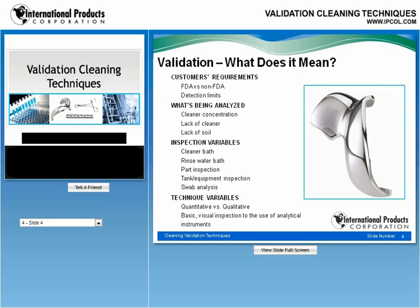We feel that these companies can be classified into two broad categories: those who are regulated by the FDA and those who are not. In general, it means that the detection limits for both of these groups are vastly different. Typically, FDA-regulated companies have very low detection limits. They need to know what the parts per million or even parts per billion concentration of cleaners are, versus non-FDA-regulated industries, whose concentration requirements are usually in the percent.